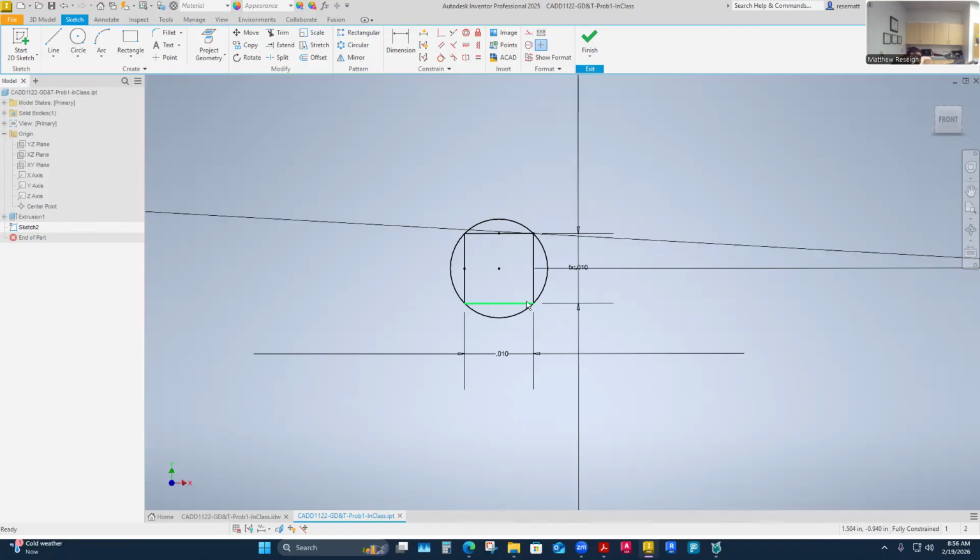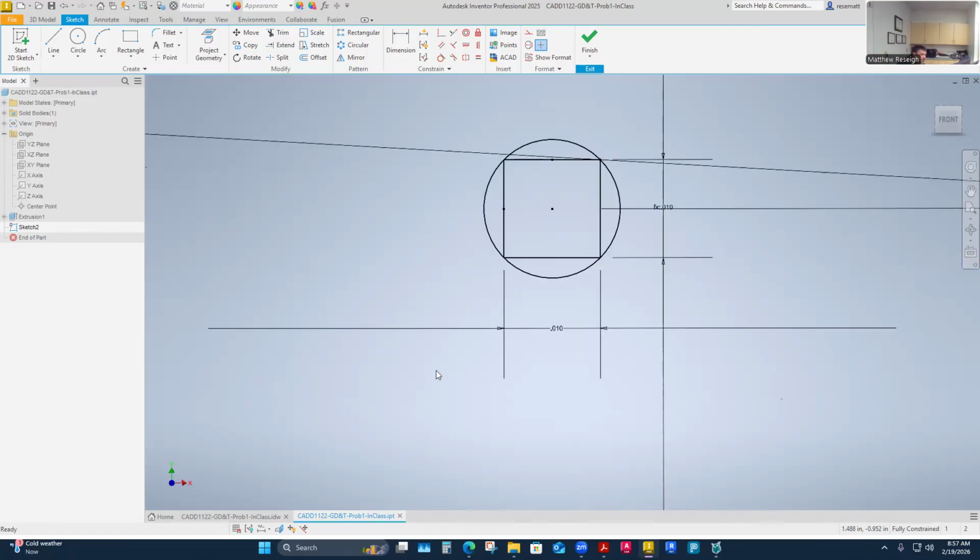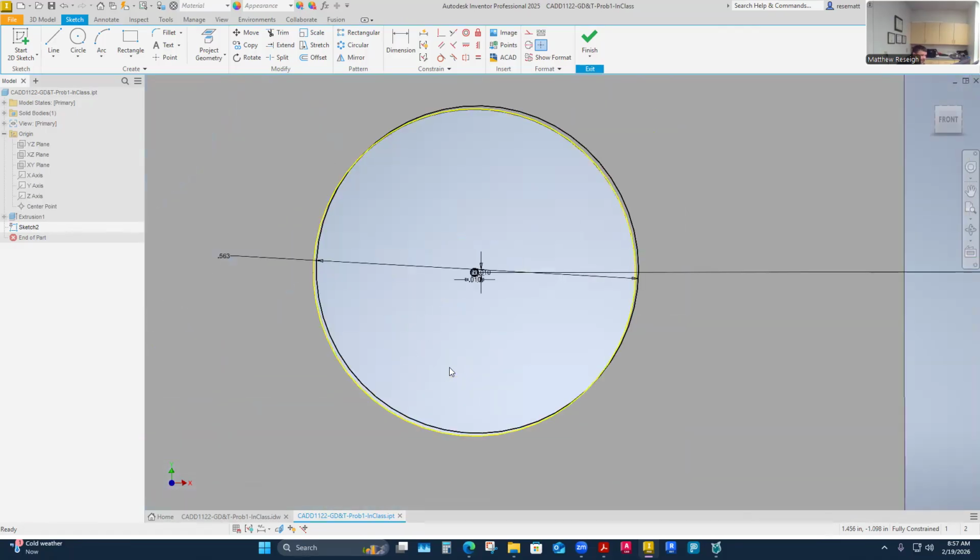If I could only pull one thing out of GD&T and drafting, it would be this concept of locating a hole with a GD&T positional tolerance. It increases the acceptability of your part, right? Because if the hole was out in here with a rectangular tolerance zone, it's essentially a rejectable part. It doesn't hit my tolerance zone rectangle, so I'd reject it. However, if I make my tolerance zone round, I get so many more acceptable parts. And so that is my study of that.